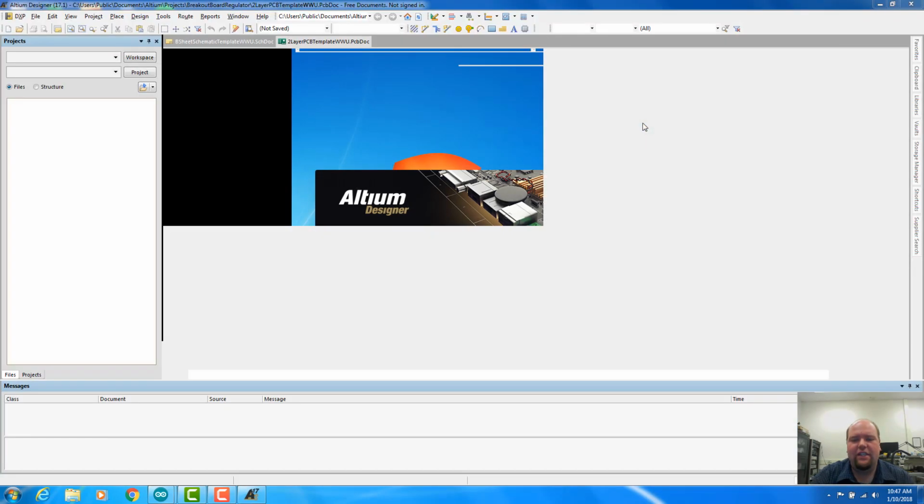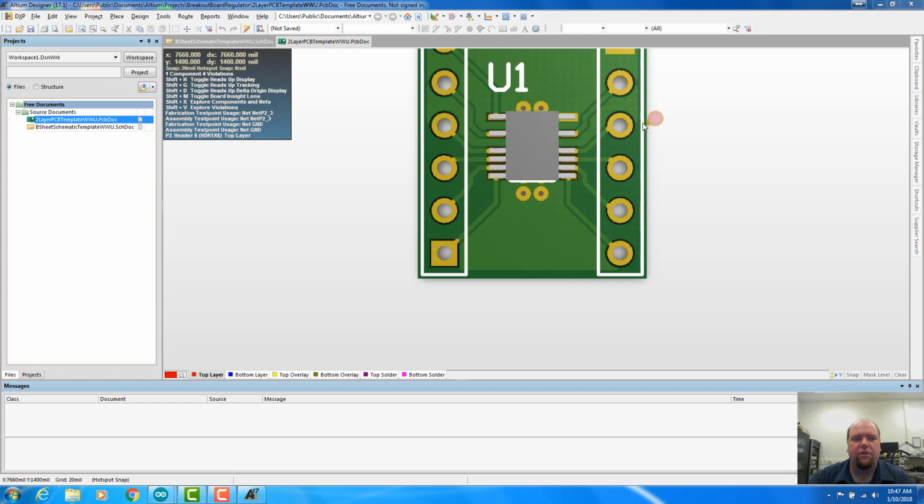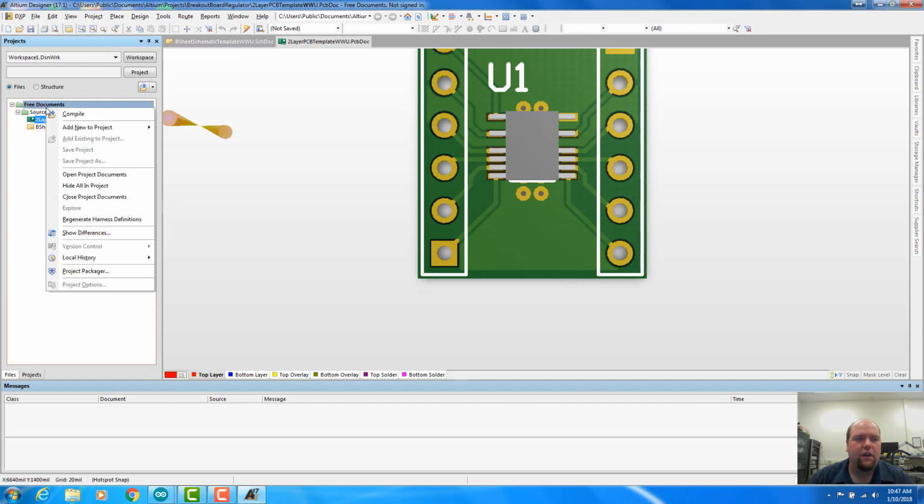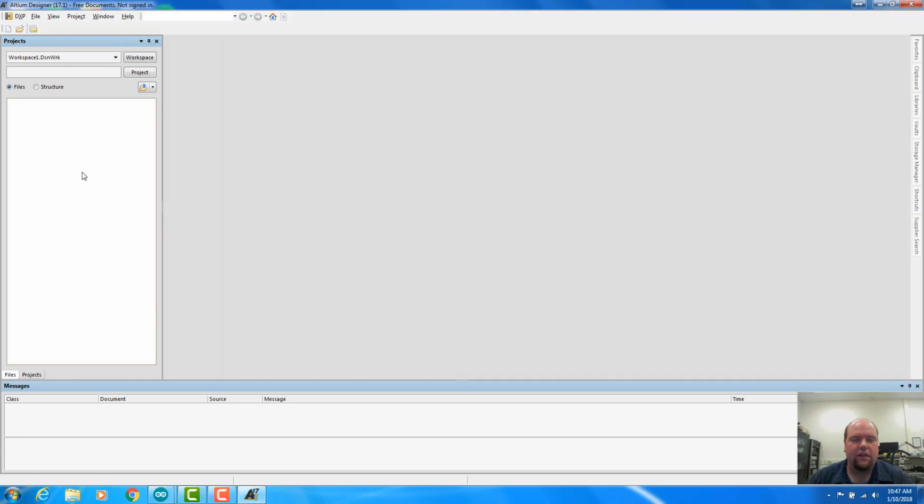And what the software does is it maps basically the logical pins. I tested this before I started it up, so it kind of showed where we're going there already. So the software basically connects this sort of logical description of the part in the schematic with the physical definition of the part that's in the footprint, and that connection is done using a pin map.